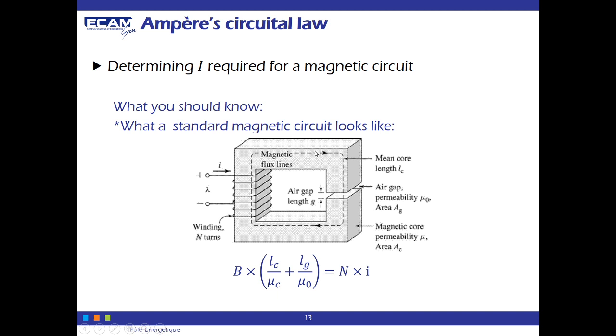In this circuit, we do not have a single reluctance since, as we said, even air is possible to magnetize, but it's very, very difficult. You will need quite a lot of energy, both electrical and magnetic, to magnetize the air, because the permeability of air is very, very small. There will be two reluctances defined in this magnetic system.